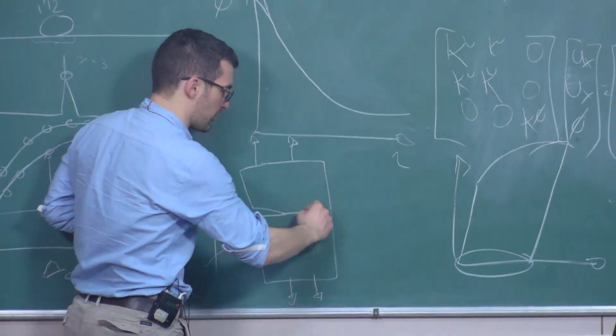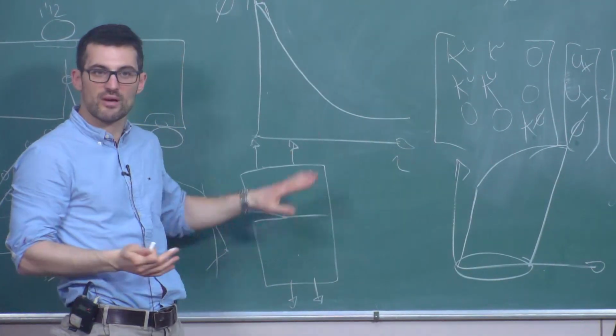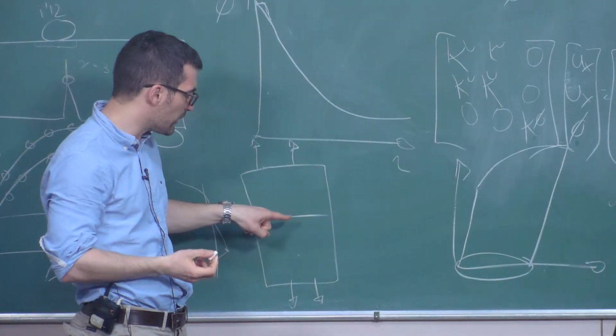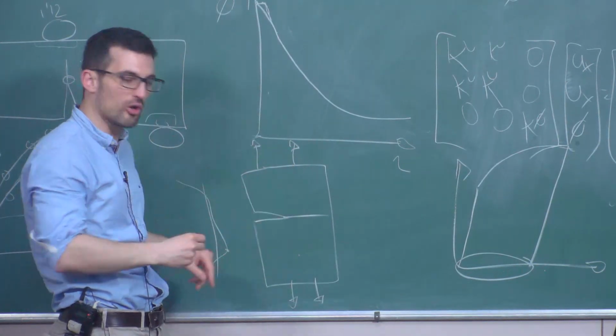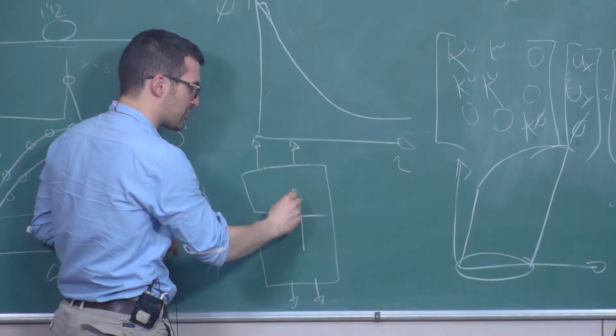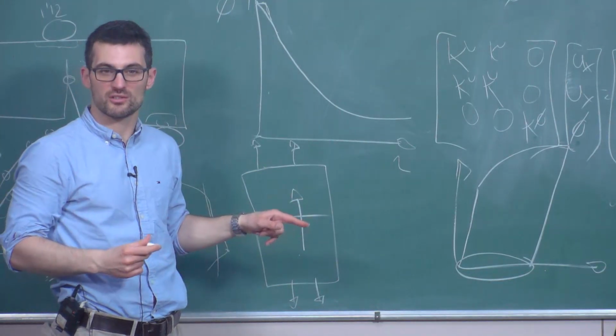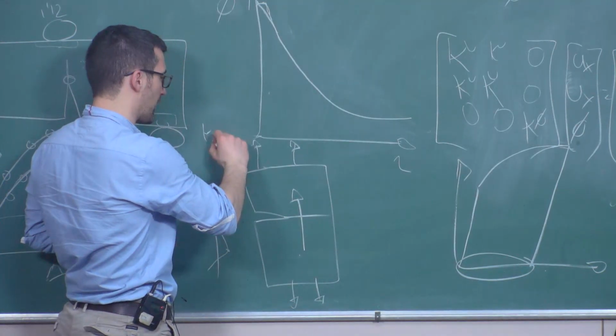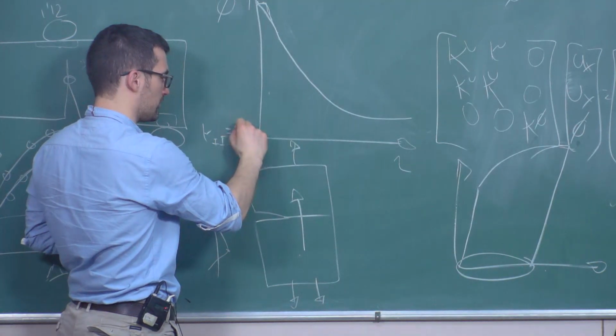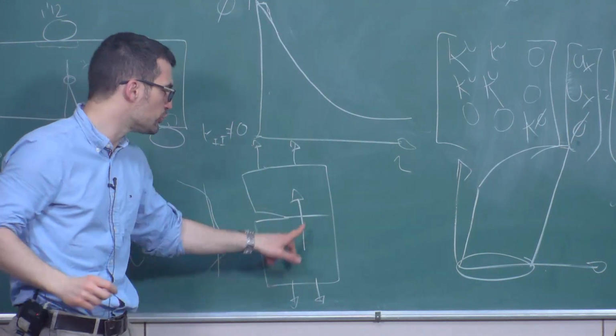You would expect your crack to grow like this, and that's fine if you have a homogeneous material. But if you have a material where you have a spatial variation of material properties, for example, your Young's modulus is going in this direction, then if you calculate the stress intensity factors, you can do that quickly in Abaqus, you will see that you don't get K2 equals 0 anymore. You get something that is non-zero due to the gradient in properties.